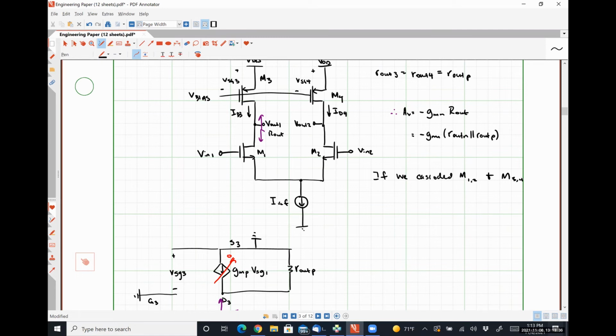Because we'd have to bias both of the transistors in our PMOS cascode and the top transistor in our NMOS cascode, which is going to crunch our common mode range that we can actually use, because we're going to have it fall between the highest bias voltage for the NMOS and the lowest bias voltage for the PMOS.